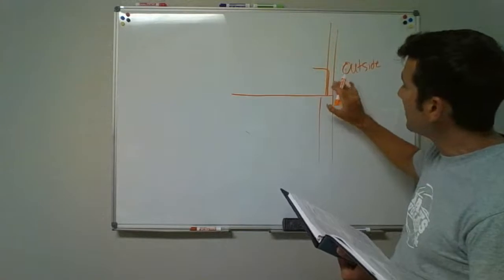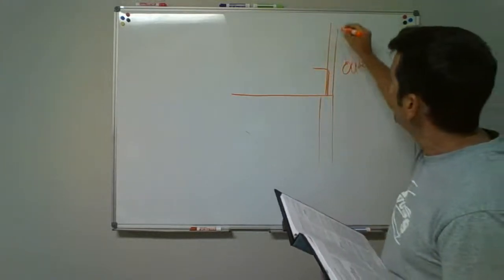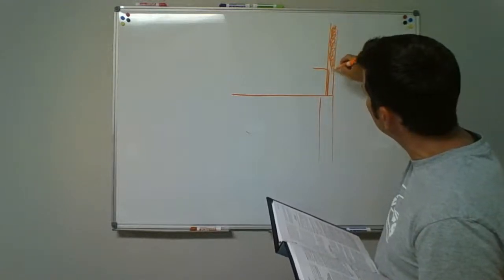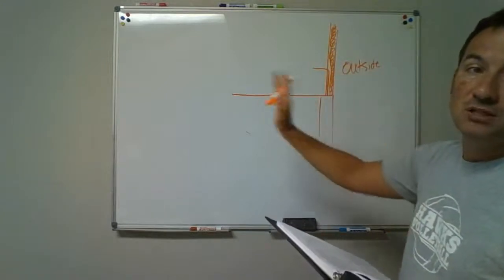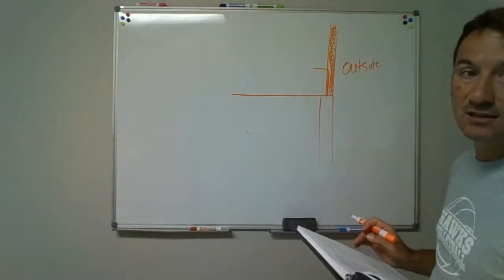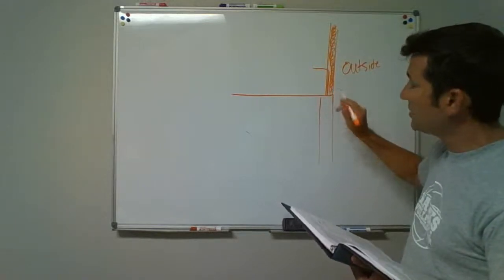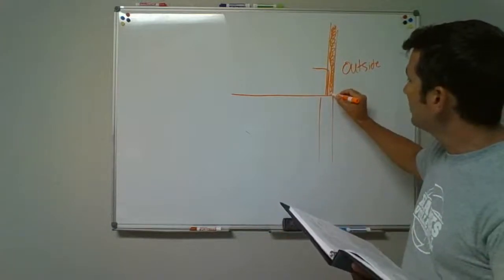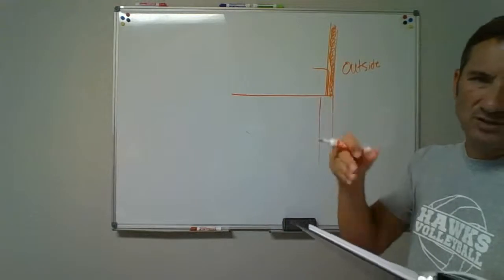We need to have that water line as far to the inside as possible. When the insulators come in, they need to put this insulation in here to where our water line is pulled to the heated side of that. We want to make sure that they can put that insulation back in there loosely. If we say, well, hey, my water line's way back there close to the back of the wall, they could still kind of shove it and tuck it back there.